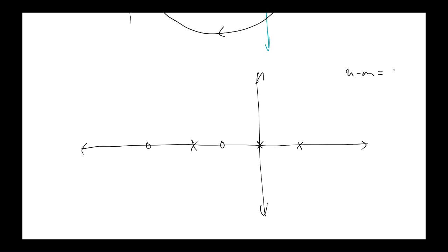I've made it equal to 1, right? Because I haven't put a pole to associate with this guy here. Right, so I've got 1, 2, 3 open loop poles and 2 open loop zeros, so the relative degree is equal to 1. So this only has 1 asymptote that goes towards the 0 at minus infinity. All right, so this guy does always behave like this.